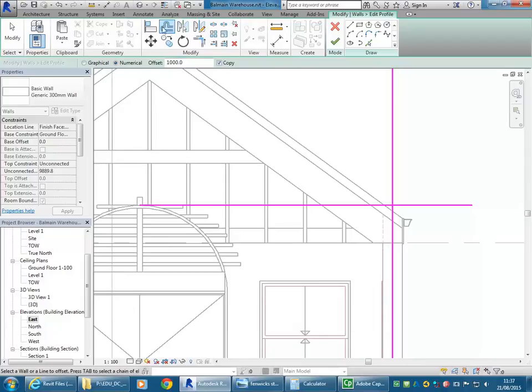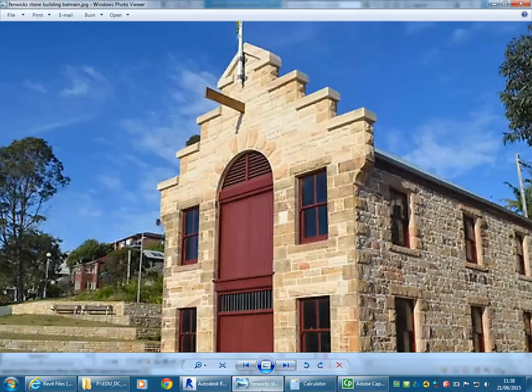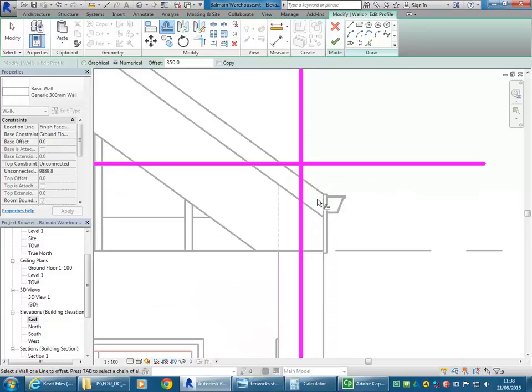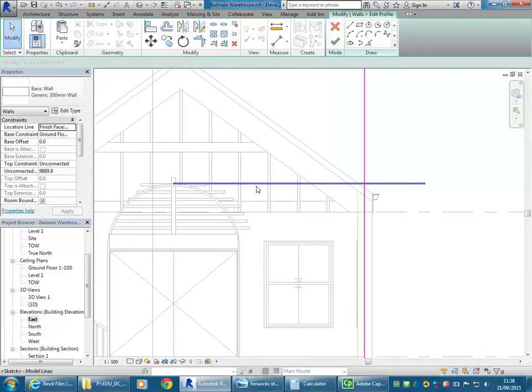Yeah, sure. So here with offset, I'm going to turn copy off, and I'm going to change that offset value to 350. And then selecting the line there, well, you can see already we've got an issue. The building in reality is a bit different to what we can really do, because the gutter there has ended up being lower than the up. So, okay, that's what's happening in reality, but I can see straight away that it's too low. So I'm going to keep it at that height. That's good. And we'll go the other way.